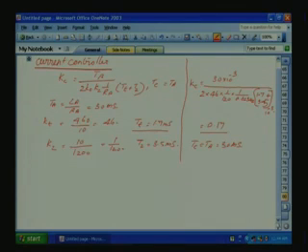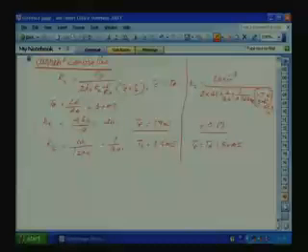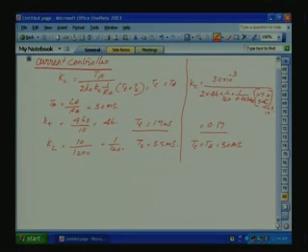See, we know the PI controller. We will go back to our PI controller and we can design our values. See, this is our V in, that is our current reference is coming, okay, we will draw it here, current reference is coming, okay. And we said reference also we want to filter with the same time constant used for the current feedback, okay.